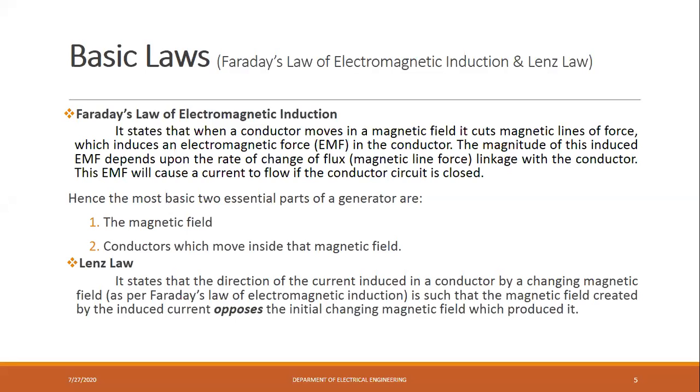Whenever a conductor moves inside the magnetic field, at that time it cuts the magnetic lines of force, that is, the magnetic flux. Due to that there is induction of EMF. Okay, so the magnitude of that induced EMF depends upon the rate of change of magnetic flux linkages with the conductor. Also, due to that EMF there is a reason for current to flow in the circuitry, when that circuit is in closed condition.